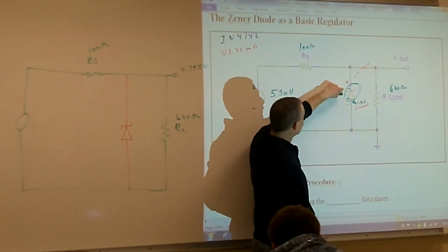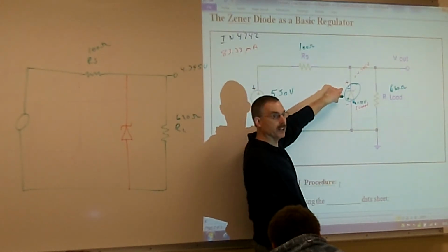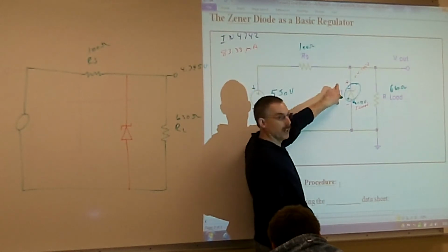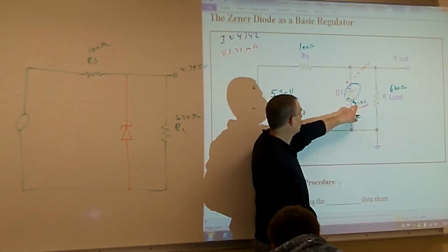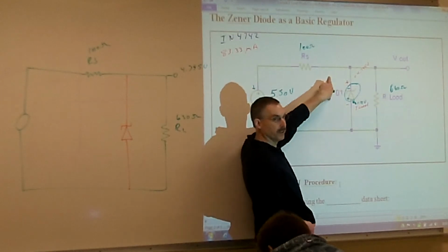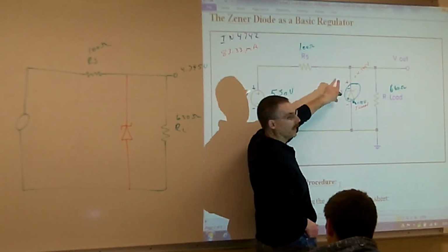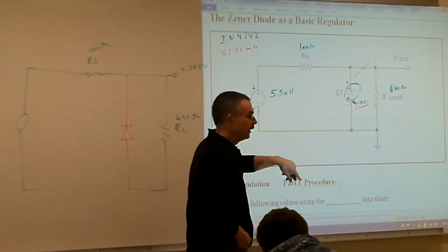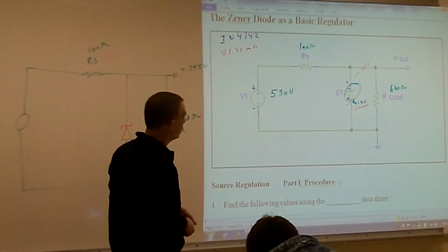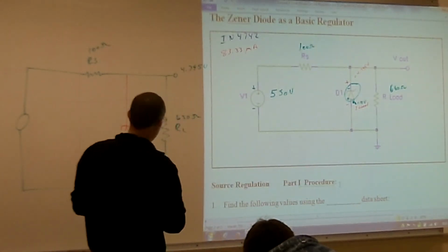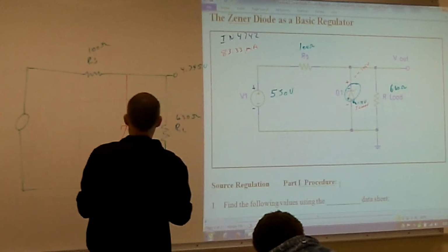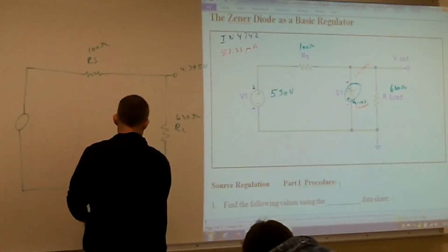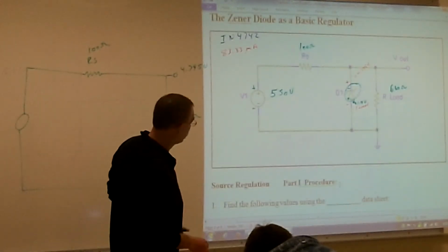And so then I've got to look at it. Could it be a Zener? Well, I've got to make sure I have a voltage potential of greater than 12 volts. And do I have a voltage potential greater than 12 volts? No. So then I know at that point it's either a diode or a Zener, and it's a no-go. So now I'm back to my equivalent circuit at this point. That diode is just going to act like it's out of the circuit.